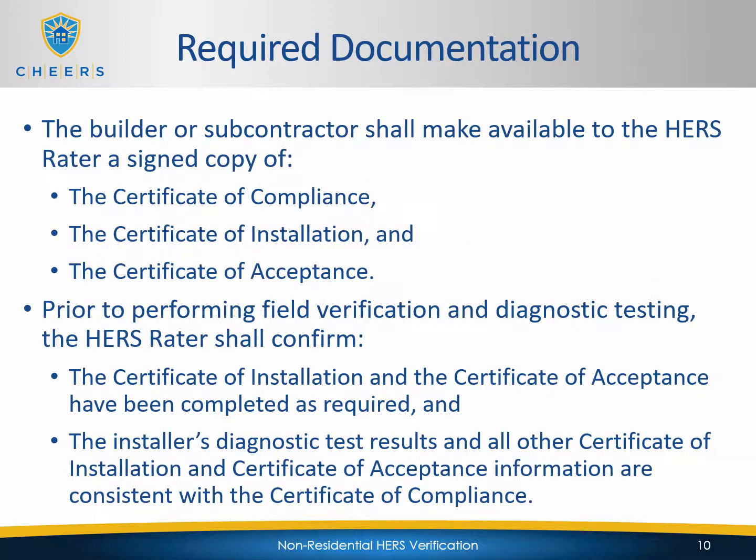The builder or subcontractor shall make available to the HERS rater a signed copy of the certificate of compliance, installation, and acceptance. Now, prior to performing field verification and diagnostic testing, the HERS rater shall confirm that the certificate of installation and certificate of acceptance has been completed as required, and the installer's diagnostic test results on all other certificate of installation and acceptance information are consistent with the certificate of compliance.